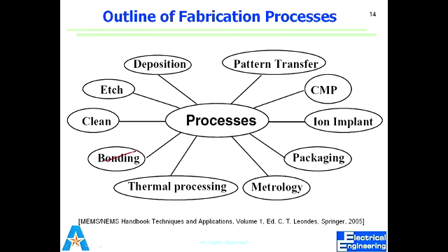So this is something that gets translated from the design of the circuit into a physical depiction of how it should be. What do we do? We make a thing called a mask set. Masks are transparent slides or plates on which we make these designs. Some parts of it are opaque, some are transparent. We use that to transfer our design onto our wafer.